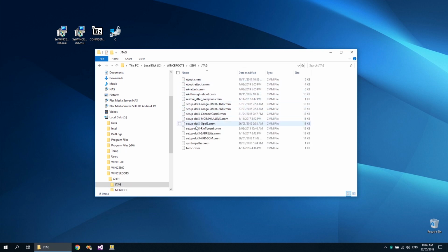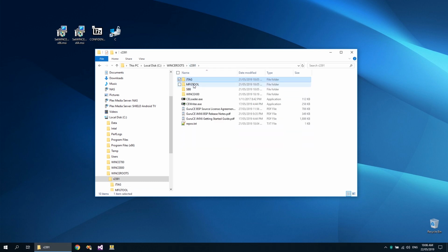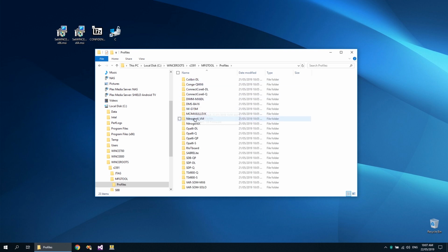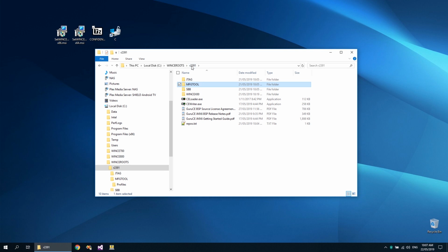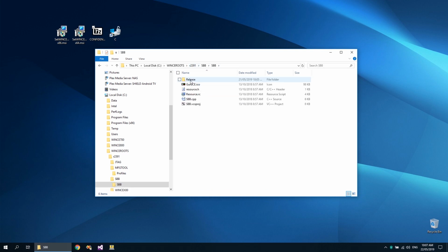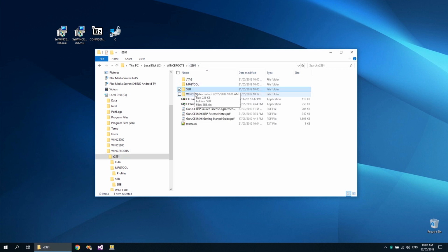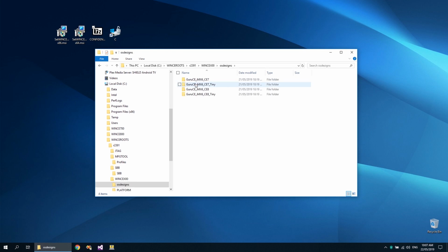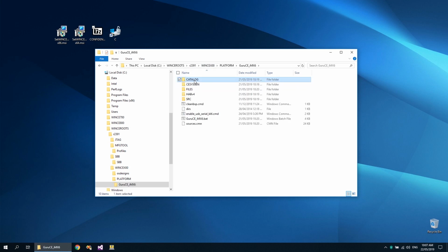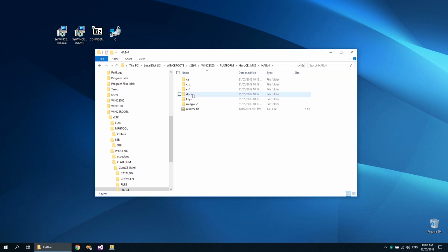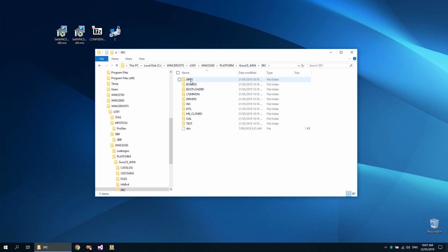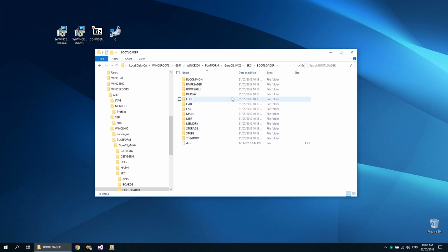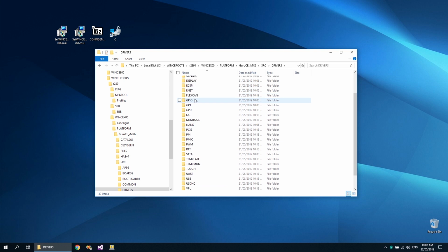Inside the BSP package, you will find Lauterbach Trace32 JTAG scripts, manufacturing tool profiles for all the off-the-shelf boards supported in the GuruCE iMX6 BSP, full source code of the silent bootloader utility, 4 sample OS designs, and of course the full source BSP itself with the extensive catalog, HAB v4 support files, bootloader source, and drivers for many external peripheral chips and nearly all modules inside the iMX6 SoC.